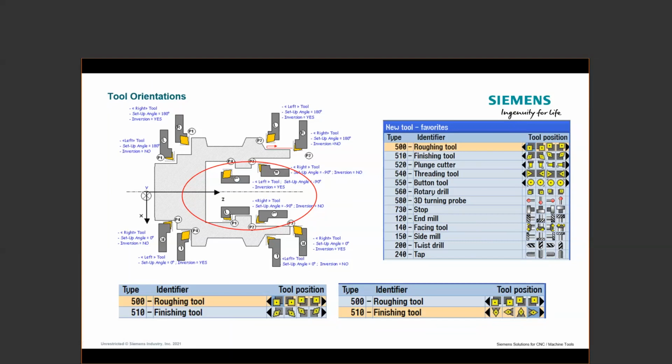Now, certainly, if I'm not using a handed tool, you can then expand further and get to your neutral orientations. We see that on the far right side of the screen. So there's a lot of different configurations. If I'm back turning, then I might use that fourth icon over. That would define a back turning style tool, or maybe I have a main spindle and a counter spindle. I mean, that's where you get into all these different orientation positions. But just knowing that little trick that, hey, that third position from the left always signifies an ID tool, it's typically what you're going to use when you start to build up these tools.